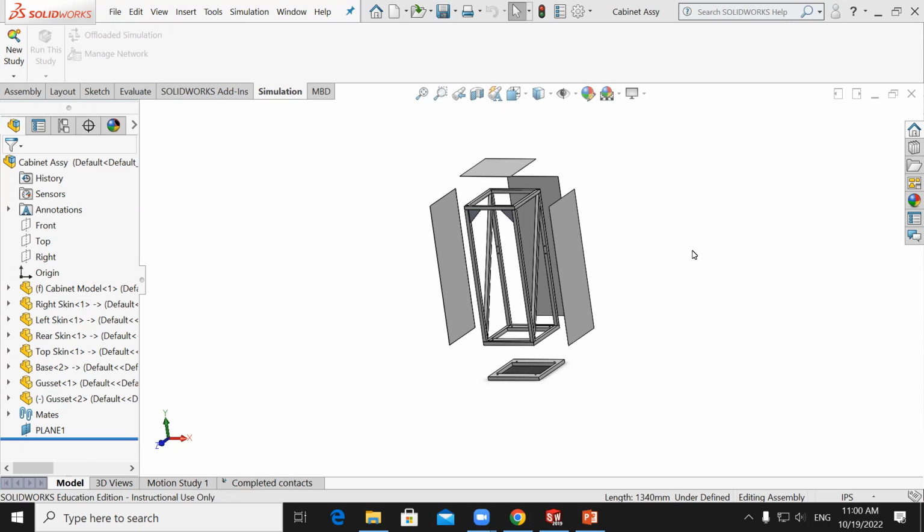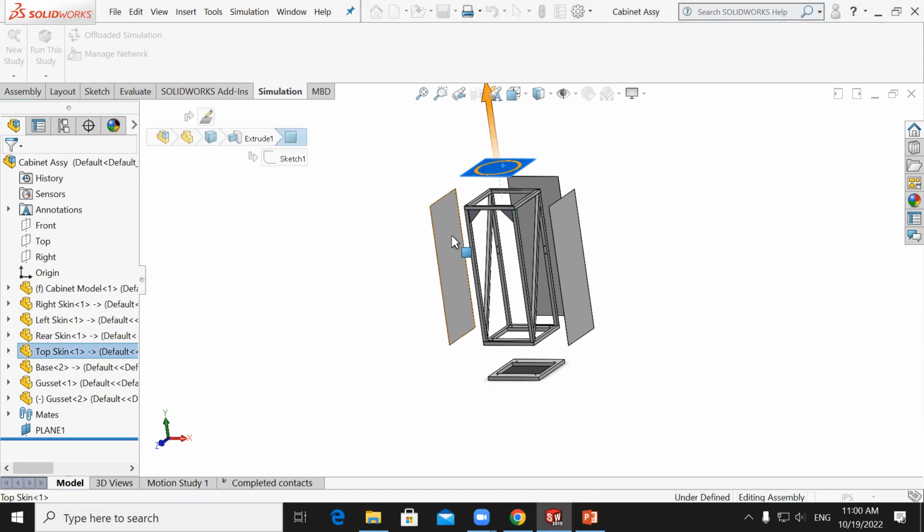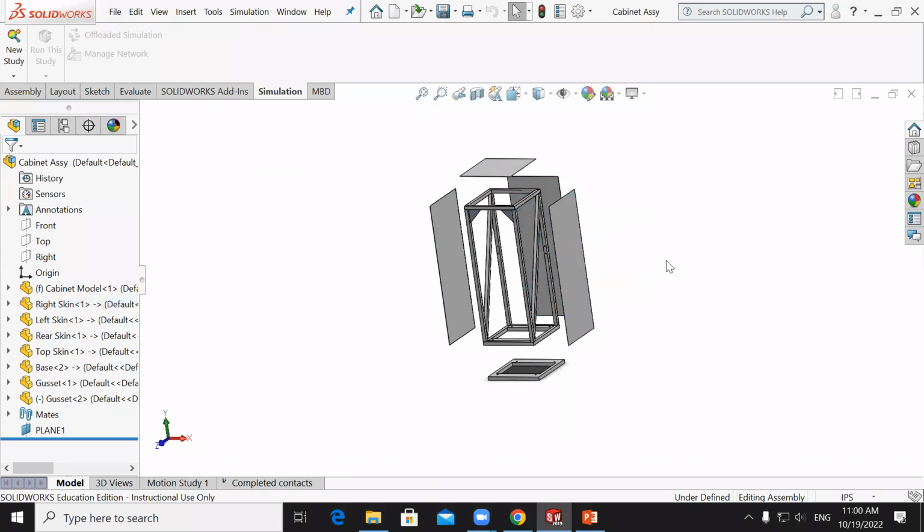That we can see the surface on the sides. So we have the top one, right side, left, and the round one. That should be surface. And if you compare, the element should be shell element, right? And the structure here should be beam element. And for this one, it's a gusset. We can use solid.